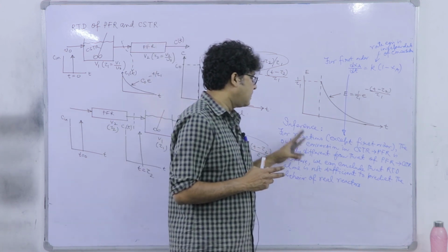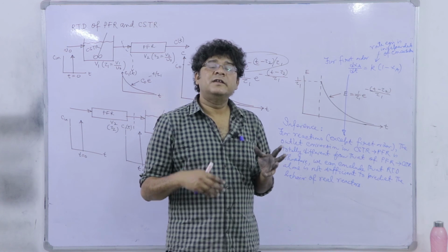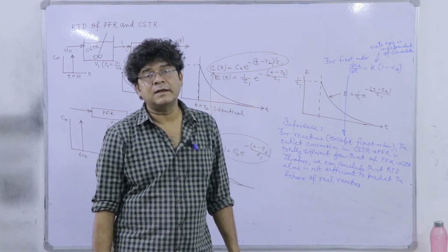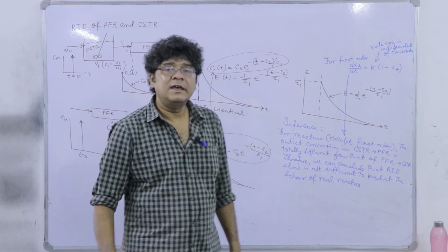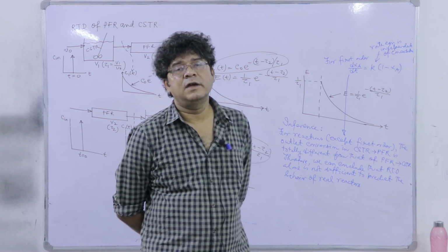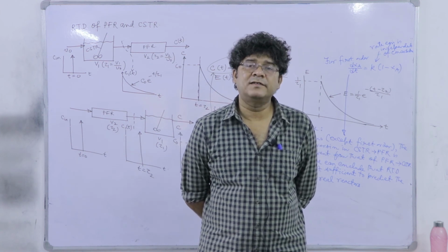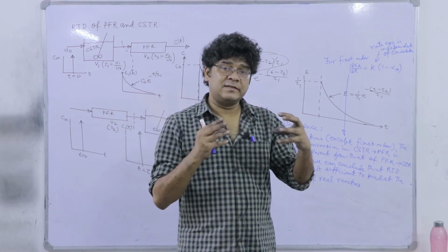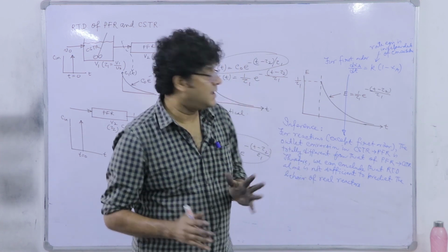So, what does it mean? It means that we definitely need RTD, and RTD will give you the distribution of residence time: how long, or what is the probability, of a specific reactant packet to stay in a reactor for a specific interval of time. That is E dt; we know what information RTD is providing. E dt provides the probability of a reactant packet to have a residence time between t and t plus dt. But how those packets having different residence times interact, that information is not included in RTD analysis.